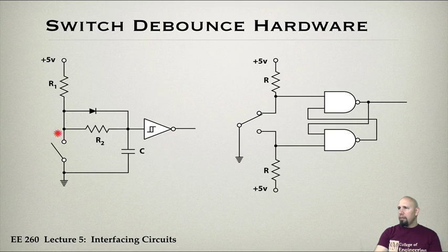What this does here is it provides a low-pass filter kind of situation. So this switch is touching. Touch, touch, touch, touch. Okay, touch, touch, touch, touch. But this signal here has been low-pass filtered. The basic idea is these contacts happen very quickly, and depending on the value of R and C, you can make this respond slowly to those taps.